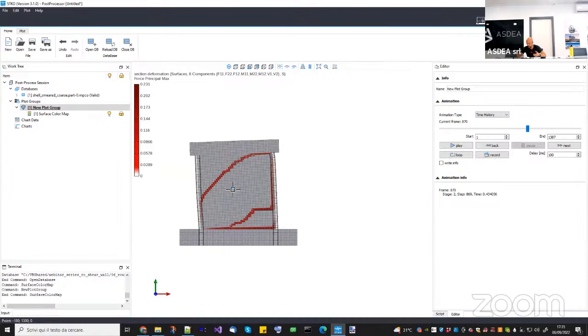it's the hysteresis loop. So with a three-dimensional model, basically the most that we can do, now I represent it as a 1D model, but basically, if I do a cyclic test in tension, then I want to consider a certain plastic deformation like this. When I go in compression, I will start from this point, so that the permanent deformation will never be recovered completely.